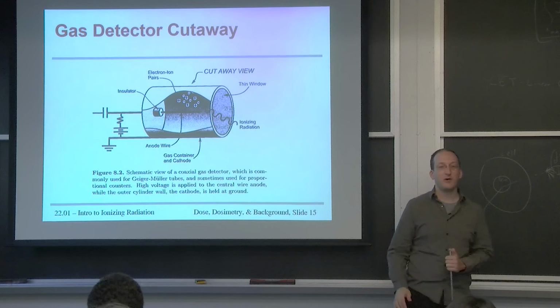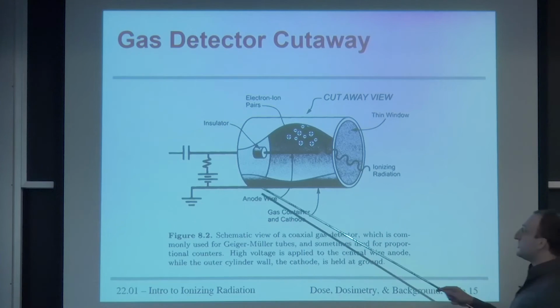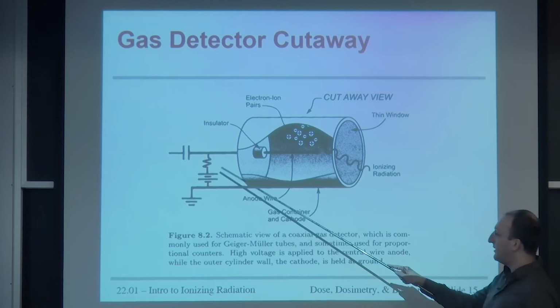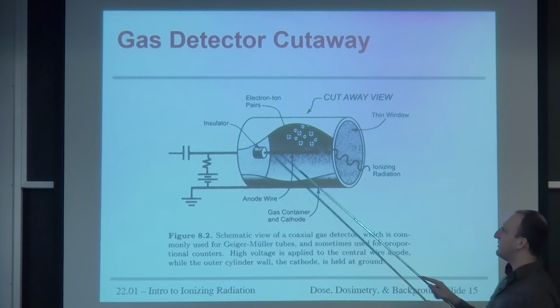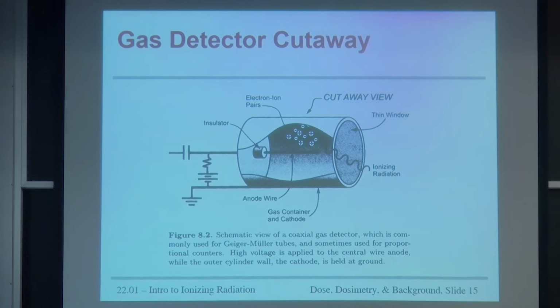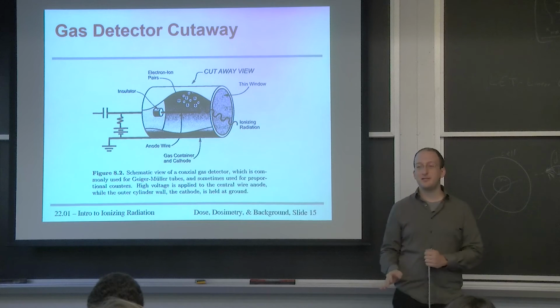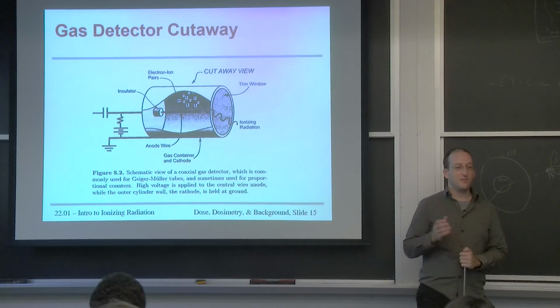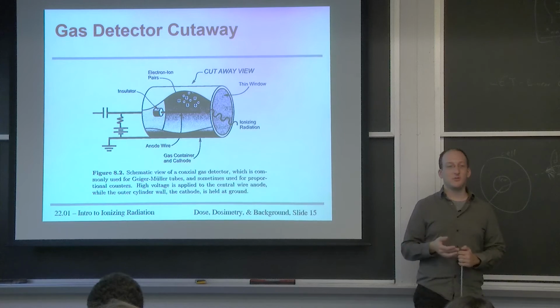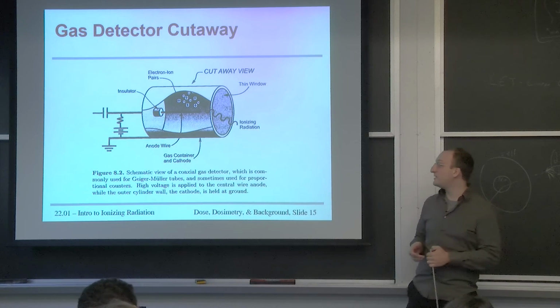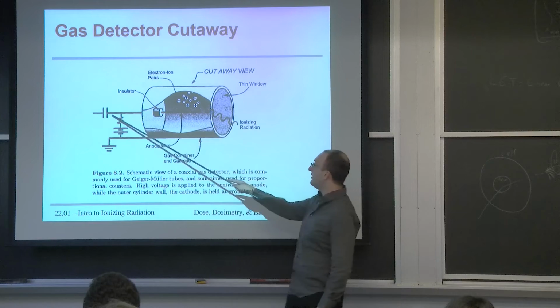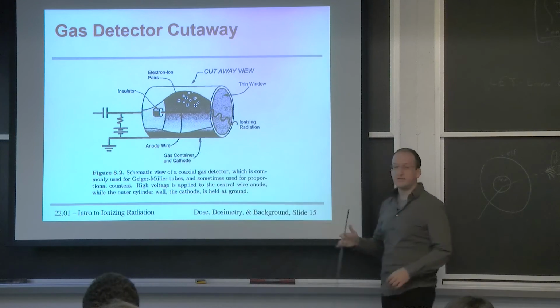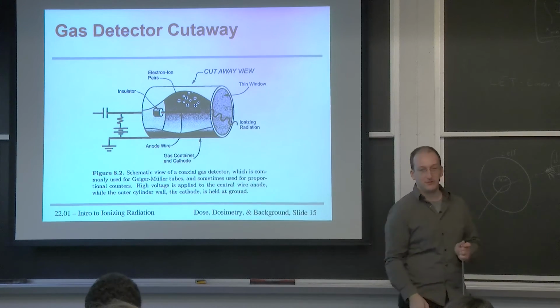And that's just a cutaway of what it looks like on the inside. And this is the circuit for a Geiger counter. There is a voltage, a resistor, a capacitor, and a tube. That's all you need. Everything else in the MIT Geiger counter is there to make lights and sound. It's just for fun. But the actual Geiger counter itself can be made incredibly compact. The bigger the tube, the more radiation it will catch just because of its size, but otherwise, as long as you get the voltage high enough to cause this ionization cascade, it works. It's really, really robust.